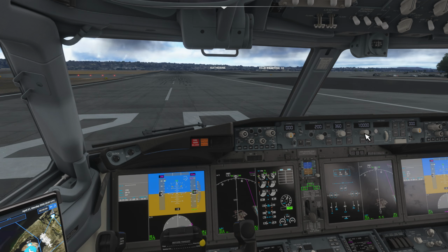We're going to start our work at 5,000, and eventually we're going to descend to 2,000, which is San Diego International's ideal altitude to approach for an ILS landing. None of this is going to kick in until we activate the autopilot system, which one of these two buttons will activate. We're going to wait till we're in the air to do that though.